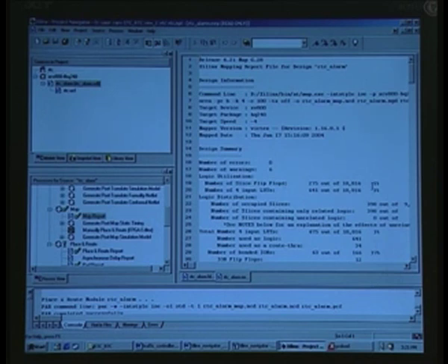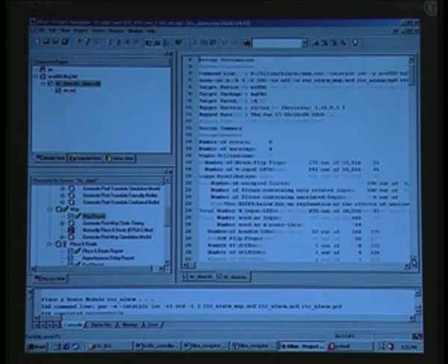For example, this RTC requires just 275 slices of flip flops out of 18,000 on the device. The device that we have used earlier was also the same device, say 800, because that happens to be the board that we have, and similarly 4 input LUTs consumed is just 641 out of 18,000 and odd.